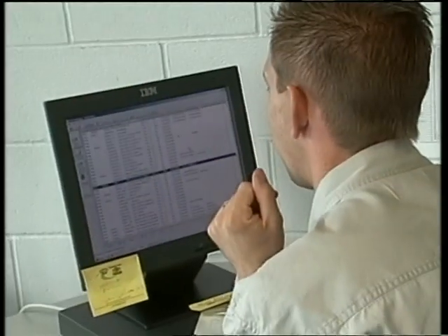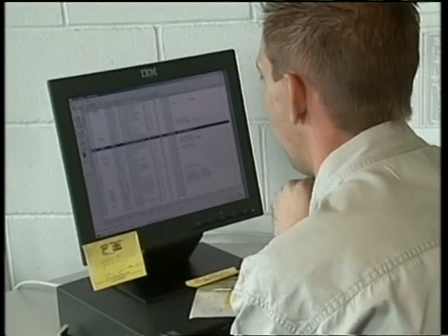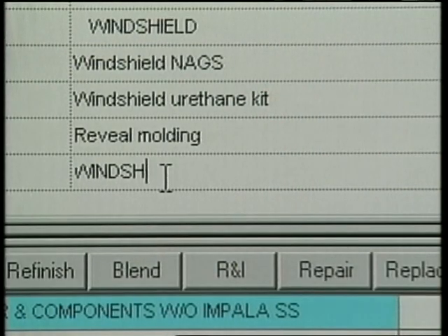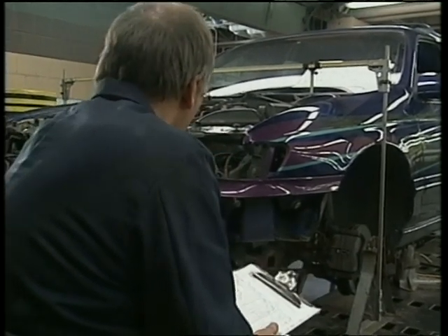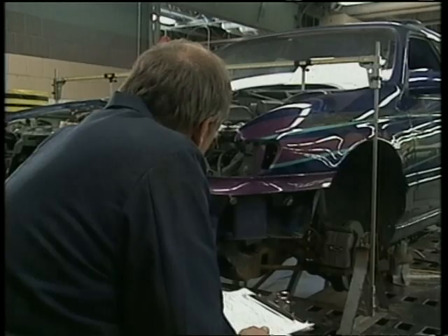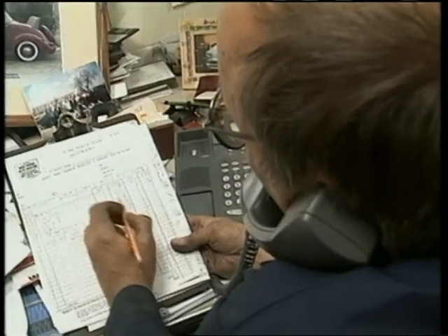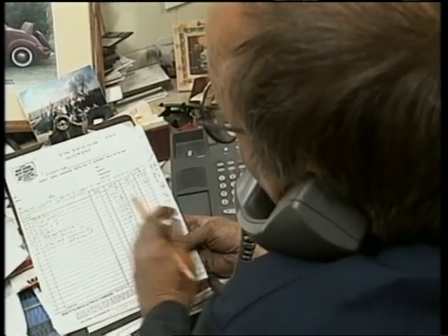You must also understand what it takes to repair that damage in hours of labor as well as parts and materials. Starting from the outside of a vehicle and working inward, list everything on paper that's bent, broken, crushed, or missing. Next to each item, list the needed repairs or replacements.